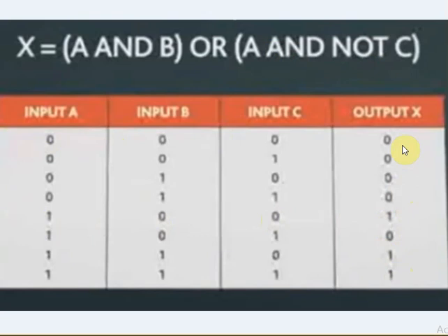Right? Very simple. First you implement the circuit, then you see the Boolean expression, how many inputs, then all possible combinations you write. After that you just consider the 2 branches, because only here you get the final output. No, there may be other stages, right? But only for the final output we have to see this and this. Then without writing any other extra columns, straight away you can place 1, after that all others 0. That is the trick.